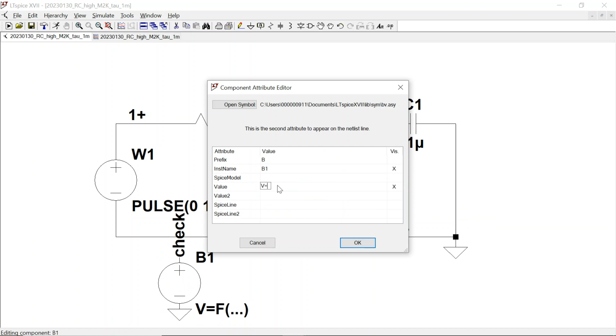So I have my DC plus 0.5 times 1 minus e to the exponent minus time. You can't use t, you've got to use minus time, divided by 10k divided by 0.1u. Oop. Now, Spice only runs from time t onward, so I don't really have to put a step function or say anything like for t greater than or equal to 0. And I need one more parenthesis. All right.